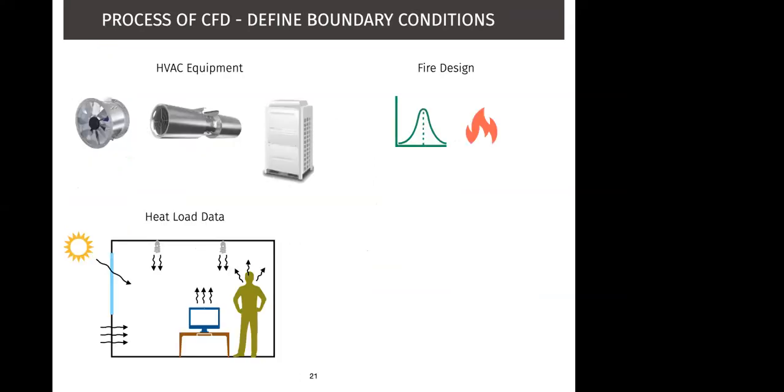And lastly, to define the boundary conditions, the ambient conditions are very important. So if you were to look at the ASHRAE climatic design data for, say, any location, in this case it's for Bangalore, you can find the weather conditions for the coldest month, hottest month, the extreme weather conditions for n equals 5, 10, 20, 50 years, and the individual weather conditions for the individual months. So these can then be utilized to form the boundary conditions for the system.